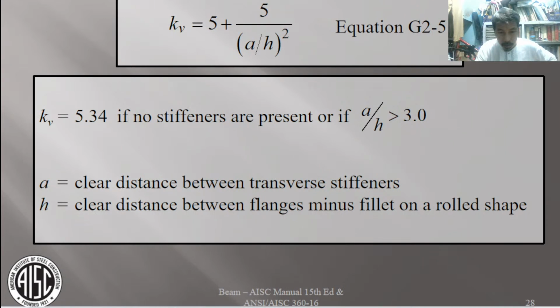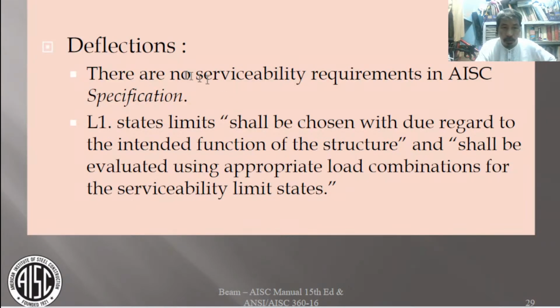Now, what does the code say about this serviceability limit? So let us look at the code. Deflection: there are no serviceability requirements in the code. There is none, so there is no provision. L1 states limits shall be chosen with due regard to the intended function of the structure and shall be evaluated using appropriate load combinations for the serviceability limit state.